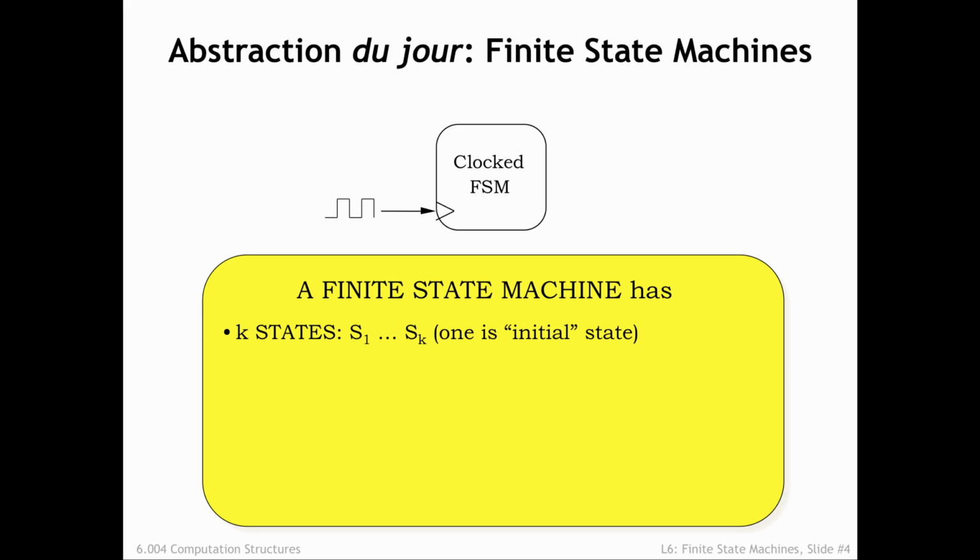One of the interesting challenges in designing an FSM is to determine the required number of states, since there's often a trade-off between the number of state bits and the complexity of the internal combinational logic required to compute the next state and outputs. There are some number of inputs used to convey all the external information necessary for the FSM to do its job. Again, there are interesting design trade-offs. Suppose the FSM required 100 bits of input. Should we have 100 inputs and deliver all the information at once? Or should we have a single input and deliver the information as a 100-cycle sequence?